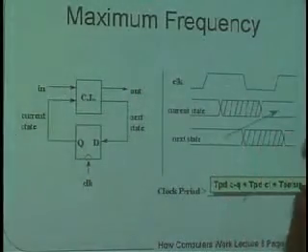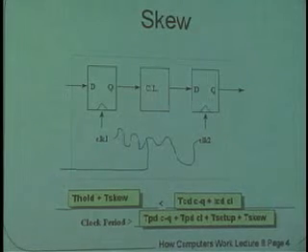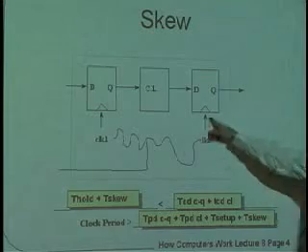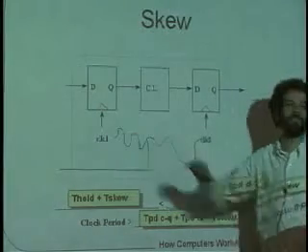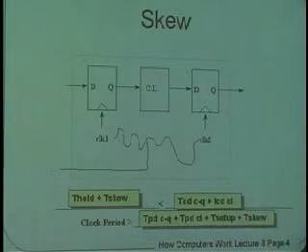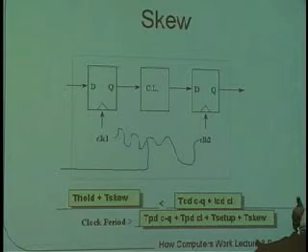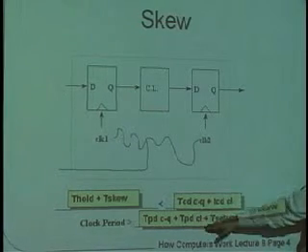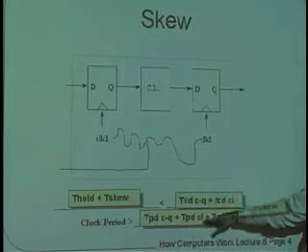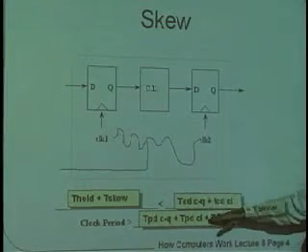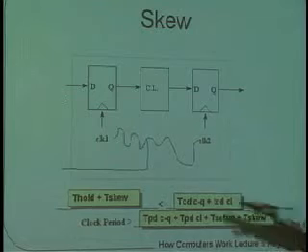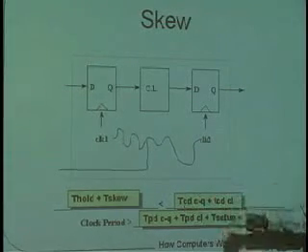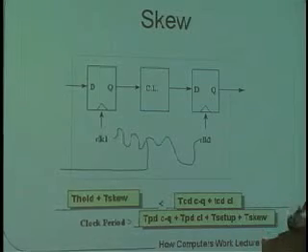And then finally, we talked a little bit about clock skew, and clock skew just kind of makes everything worse. If it's possible that this clock and this clock are not going to be hit at exactly the same time, we have to add a little bit of extra margin for the clock skew. And so these two relationships which we had before, all you need to do to understand how the clock skew makes them harder to meet is to put them up there and say, which side of the inequality should I put the clock skew on in order to make the inequality more difficult to meet?